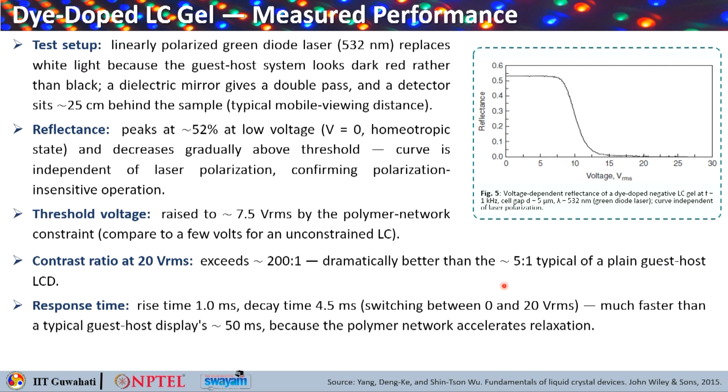Another important factor is the response time. Here you'll see the response time. The rise time is typically 1 millisecond, and you have 4.5 millisecond decay. The switching is taking place from 0 volt to 20 volt, and this is the rise time and decay time.